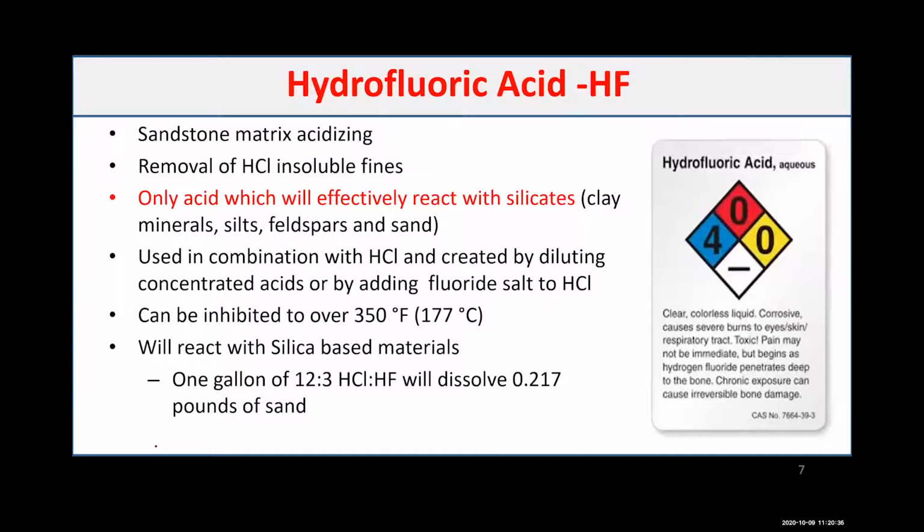The second acid is the hydrofluoric acid, HF, and it's the second inorganic acid that we use in the oil field industry. We mainly use it when HCl cannot be used or HCl cannot dissolve the material. It's the only acid system that can dissolve silica. That's why we use it mainly for sandstone matrix acidizing, because of its ability to dissolve the silicate.